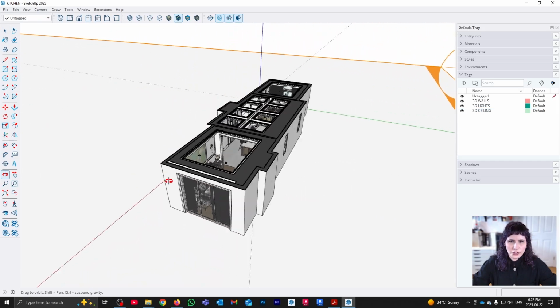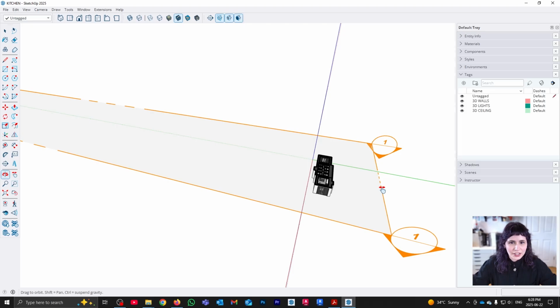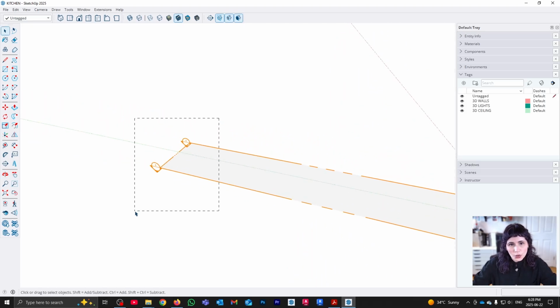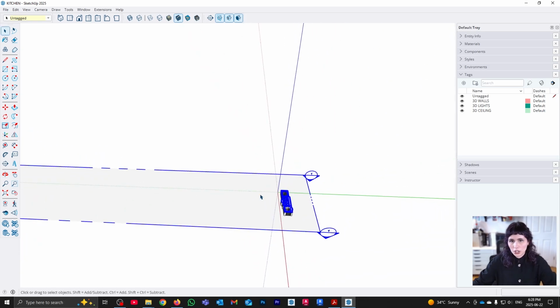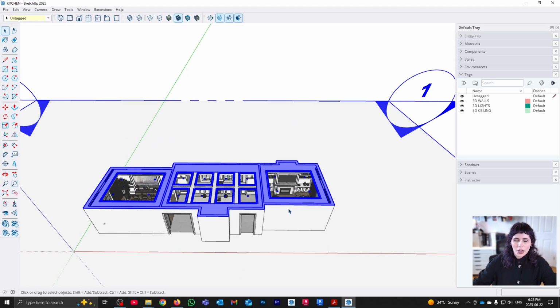This is the first very important thing to understand about creating a section plane: you don't get to control how big it is. The section plane will be as big as it needs to be to showcase the entire geometry that is in the model. For example, here I just have this space, but if I had this in another building, my section plane would become big enough to cover all of them, because it's basically like I'm doing a laser through the entire world.